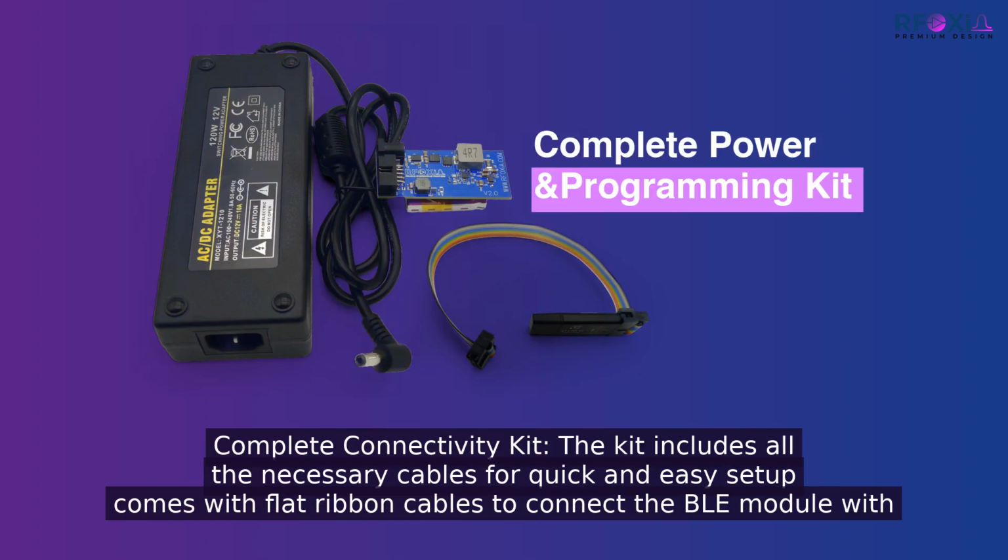This is the complete connectivity kit, flat ribbon cables that handle both power delivery and SWD signal routing between the module stack and the programmer. Flat ribbon construction minimizes inductance on the SWD data lines, which reduces signal integrity problems at higher clock rates. Everything you need to go from unboxing to first successful firmware flash is in this kit. No sourcing individual cables, no improvising. The connection is defined, repeatable, and correct every time.